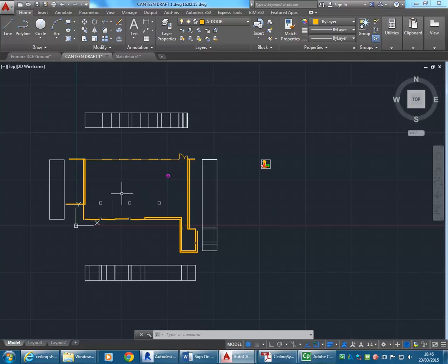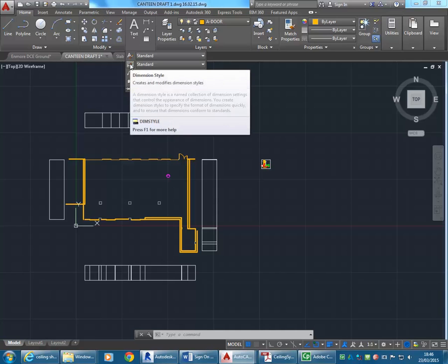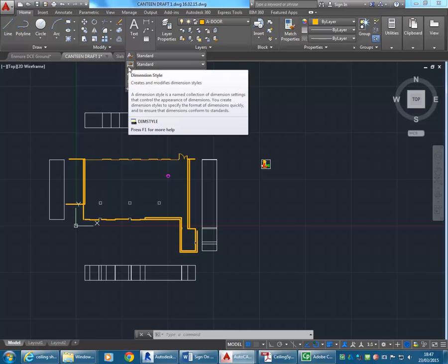But when you draw your text, you don't need to think about the scale when you're drawing it by hand. You just get your letter template out, or you draw it by hand, and it is the size it is, 2 mil or 3 mil high, depending on how legible you need it to be. So it's, again, the opposite in AutoCAD. You need to think about the scale once you go to do things like your text or your dimensions, and a few other things as well.